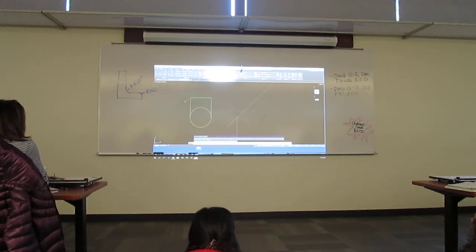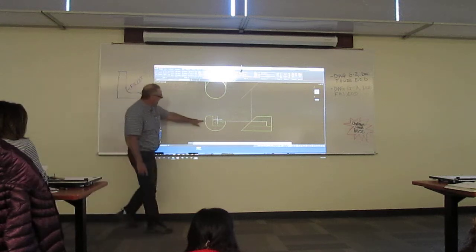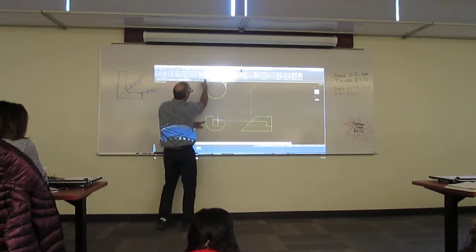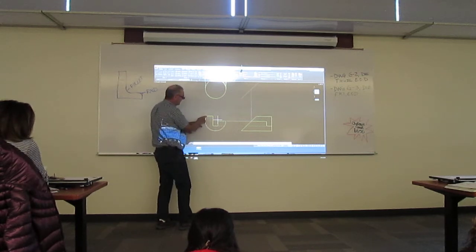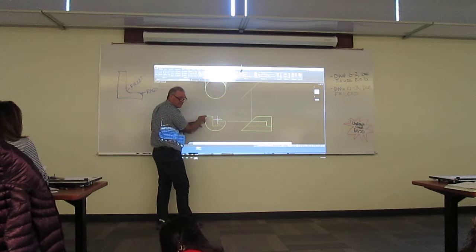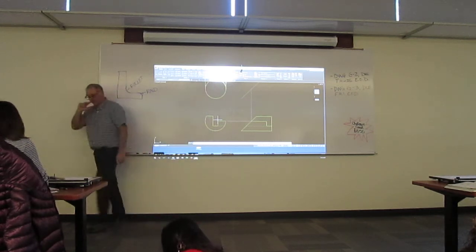Thinking that, and these are kind of done. Okay, so there's my shape so far. Now, let's deal with our cut surfaces. I'm going to pay attention again, as I look on here, where's this center line in relationship to the cuts? Because as this thing projects up through, I will have my limiting element here. That's that line right there. This thing keeps wrapping around on that curved surface to this location. So that's going to tell me where that cut really starts up here.